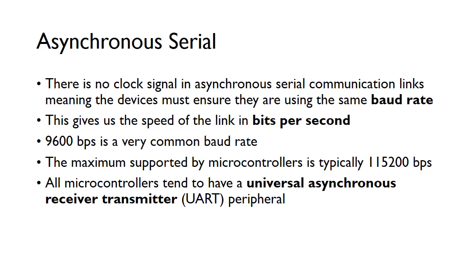And typically the maximum supported by microcontrollers is 115200 bits per second. So you can see this is nowhere near megabits per second. It's often perfectly adequate for what we need in typical applications. And then all microcontrollers tend to have a universal asynchronous receiver transmitter peripheral. So this is a common UART or just a common serial port. It's probably the most common communication protocol you use in embedded systems.